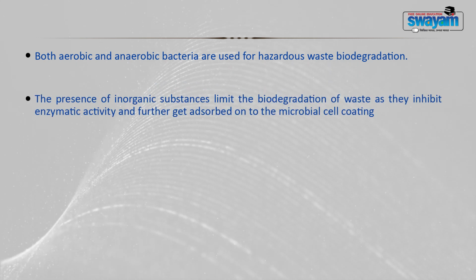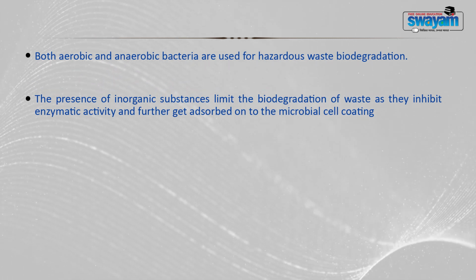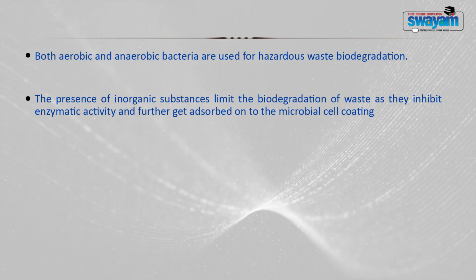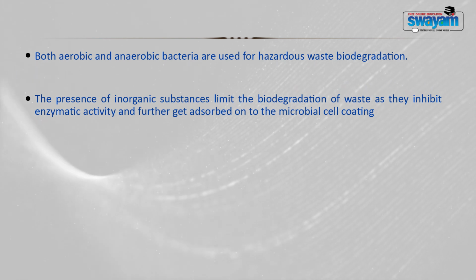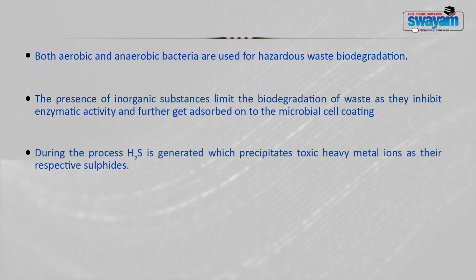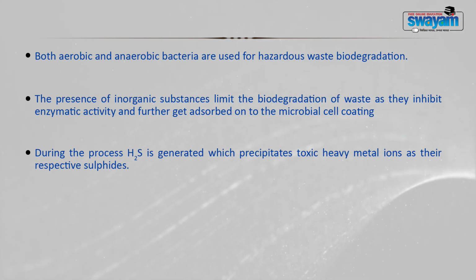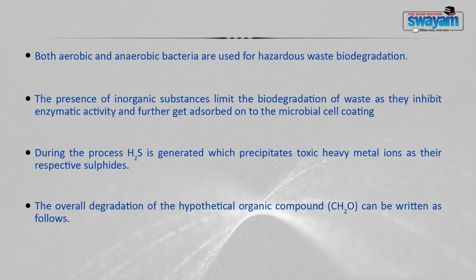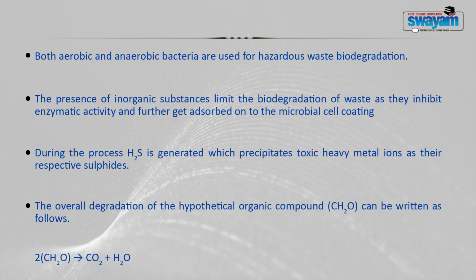Now, the presence of inorganic substances will generally limit the biodegradation of waste because they inhibit the enzymatic activity of the microorganisms. Further, they also get adsorbed onto the microbial cell coating. During the process, H2S is generated, which precipitates toxic heavy metal ions as their respective sulfides. The overall degradation of the hypothetical organic compound, CH2O, is given by the following equation.